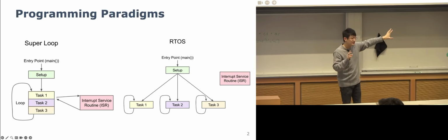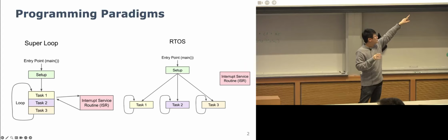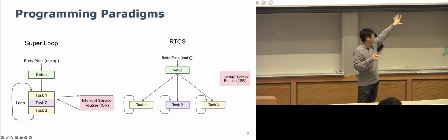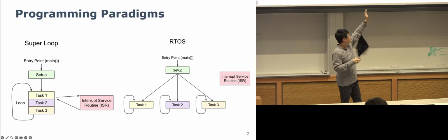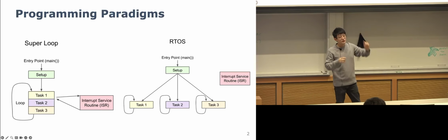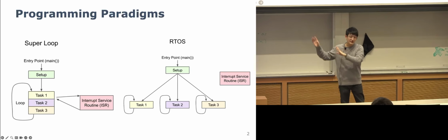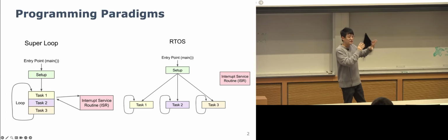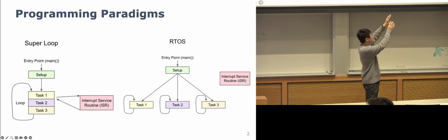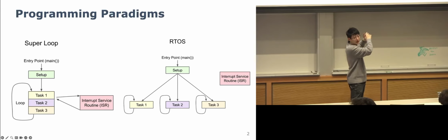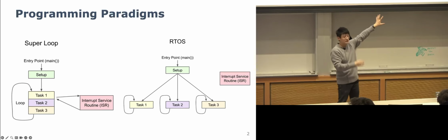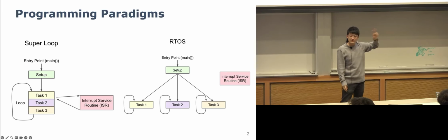What it actually does is, because it still has all those interrupts that can interrupt these parallel tasks, it's just the scheduler, which will be connected to the SysTick we will talk about in a minute. The scheduler keeps track of the latest time each task has to be executed, and when that time hits, it triggers the task to run. And it's totally possible that for a lot of the time the system is just in an idle state.